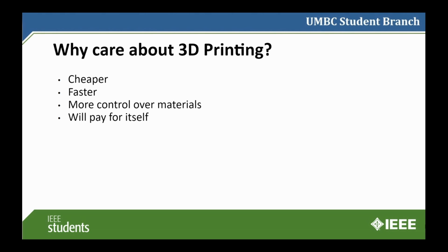Because normally, if you have a 3D printer that has one extruder, you would have to stop your print in the middle. You can program it to stop at a certain layer, and then you would have to extract your filament and put it back in. That's how you would normally do it with one extruder, to make a mixture of colors together, or to have multiple different colors in a single print, maybe like a figurine of some sort. But with the dual extruder, you have more control over what your color will look like, and the materials that you can put in, you can make, I mean, absolutely anything.